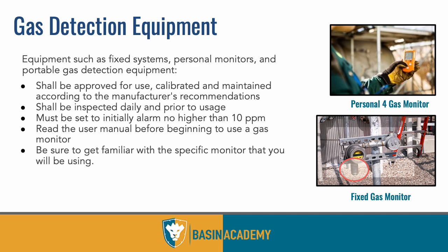Again, you can adjust the alarm, so if anything, we want to adjust that alarm to be lower than 10, not above 10. It's got to be at least 10. Make sure you know how to use that monitor before you put it out in the field or wear it. Like, if someone just hands you a monitor and says, wear this, no. You should ask, how does it work? What does it do when it sounds? Ask some questions, read the manual, be familiar with that monitor.